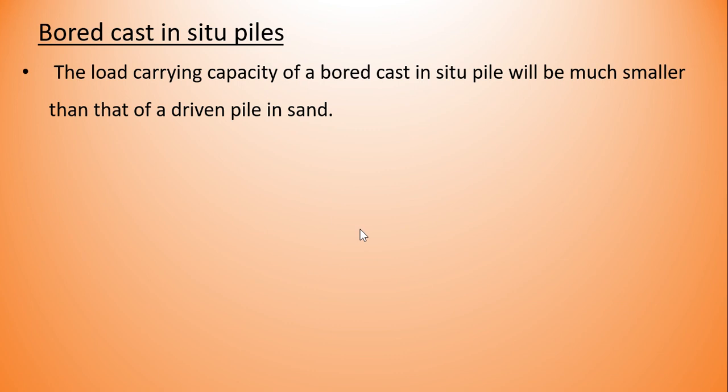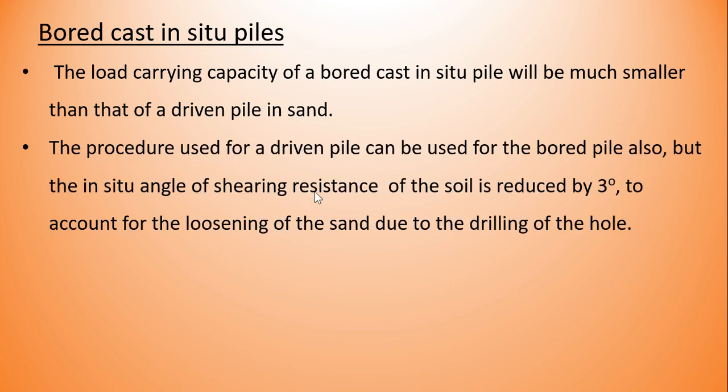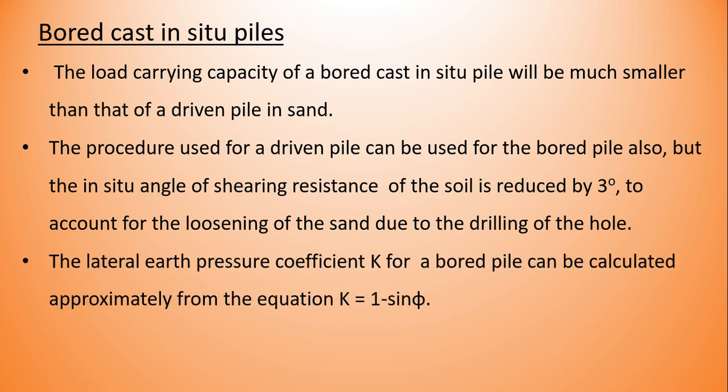Bored cast in situ piles. The load carrying capacity of a bored cast in situ pile will be much smaller than that of a driven pile in sand. The procedure used for a driven pile can be used for the bored pile also, but the in situ angle of shearing resistance of the soil is reduced by 3 degrees to account for the loosening of the sand due to the drilling of the hole.